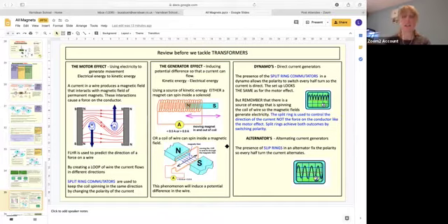Using a source of kinetic energy, which would be your wind turbine or burning your fossil fuels or wave or whatever it is, either a magnet can spin inside a solenoid, moving backwards and forwards like it is on this one here, which is what they use in power stations, or a coil of wire can spin inside a magnetic field. This phenomenon will induce a potential difference in the wire. A current will flow.